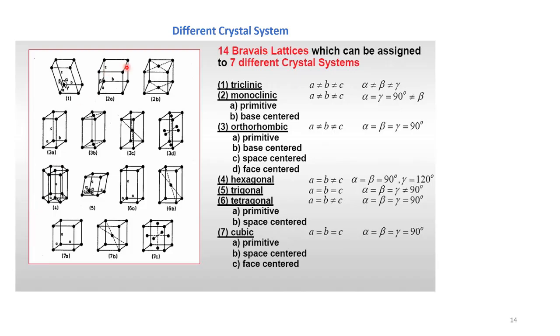So there are different kinds of structures. I only talked about the cubic structures. However, there are other rhombic structures also: hexagonal, trigonal, tetragonal. These are all different kinds of Bravais lattices. Actually, there are 14 Bravais lattices and 7 different crystal systems. I talked about the cubic one where the sides are equal, so a equals b equals c, as you can see here. And we have the primitive one, which means the simple cubic structure having atoms only on the vertices.